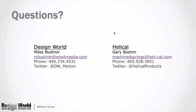Well, okay. I came into this world of machine springs trying to solve that exact problem, fresh out of grad school, and I found that there was really no system to be able to evaluate machine springs thoroughly. So we at Helical use FEA. We use very explicit FEA systems that we've put together that work, and we're happy to share those results with customers. But as far as machine springs are concerned, we use no Timoshenko's work, or Wahl's work. They'll get you sometimes in the ballpark, but sometimes not. And you don't know which one you're in until you make the part and find it does or doesn't work. So we use FEA.